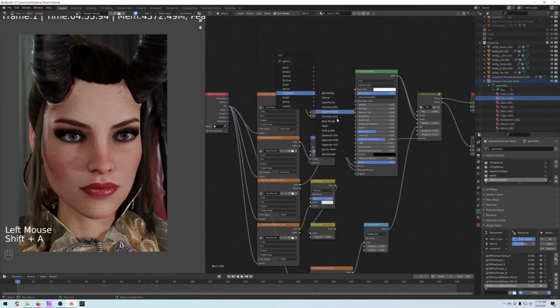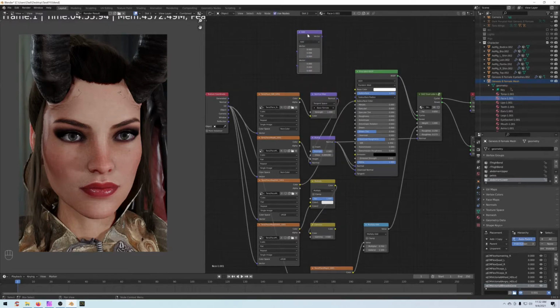So we'll add a vector math node and set it to multiply. The ratio we'll use is 1, 0.35, and 0.2, and these represent the depth that the RGB values are going to penetrate the skin before they scatter. These numbers are just the ratio between those three colors. So keep red at 1. You can adjust green up or down a little bit. You can adjust the blue up and down a little bit depending on your character and your skin color and what you're trying to achieve.